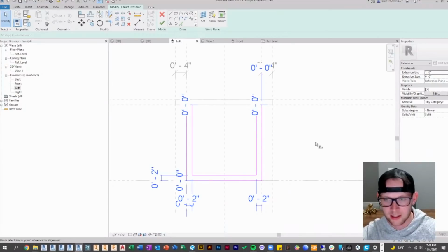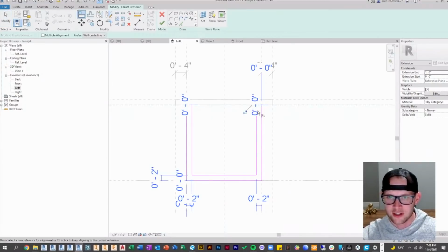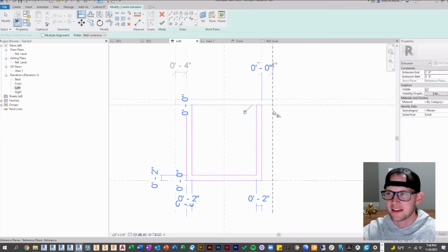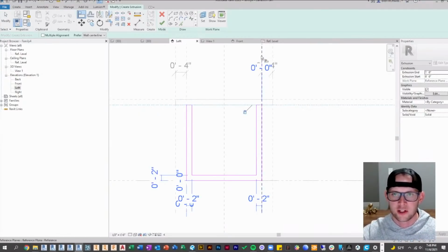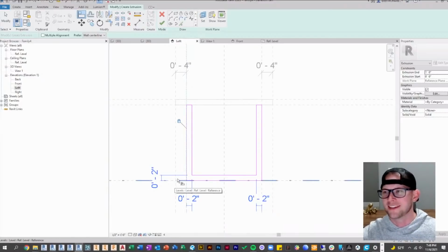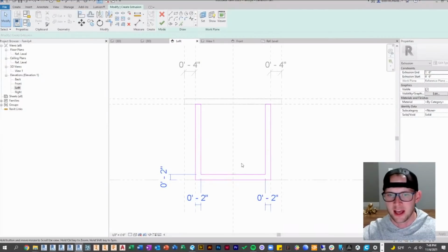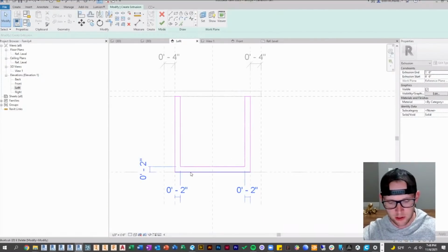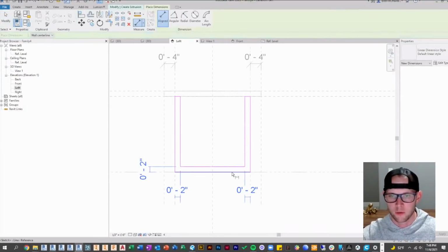So we're going to really quickly constrain this sketch. And you can see when I make the constraint myself, the assumed relationship disappears. So this is a good way. You can also troubleshoot this way. If something's misbehaving and you can't quite figure it out, usually I do this with arcs or circles because I can never quite tell what Revit is doing sometimes. And this will sometimes give you a clue of what's interrupting your workflow.